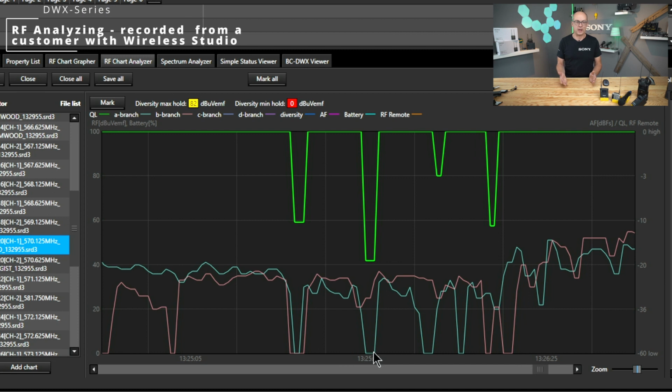If the noise is very high, you can't understand what the person on the other side tells you if the noise in the environment is high enough. And here, this is the same thing. So the minimum you need is 20 dB, better 25, I would say. Then you're on the safe side. Technically it is 20, but from my personal experience it's 25.